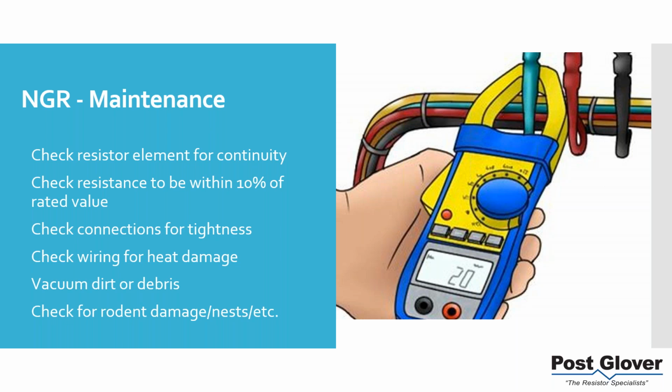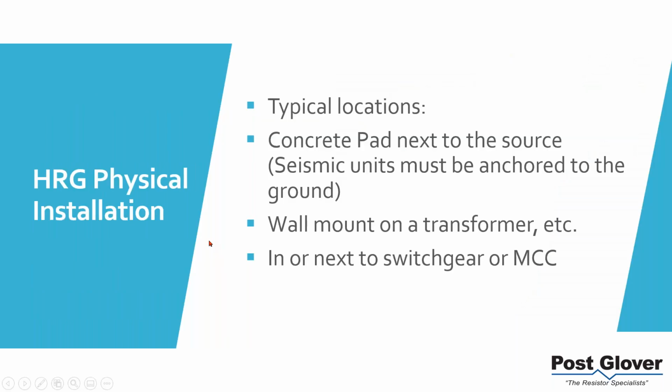We need to have airflow to actually cool off the resistor. So it is possible for very small things to get in there. It's also possible to get screens, etc., but you have to specify that when you get the unit, because all that stuff impedes airflow. So we may need a bigger resistor if we're having screens, etc. So just food for thought.